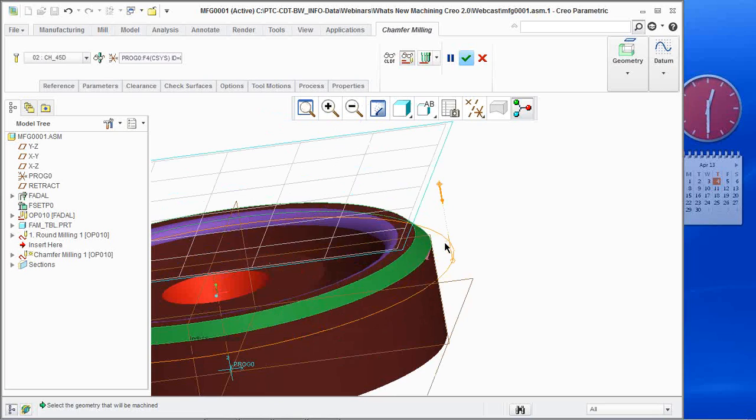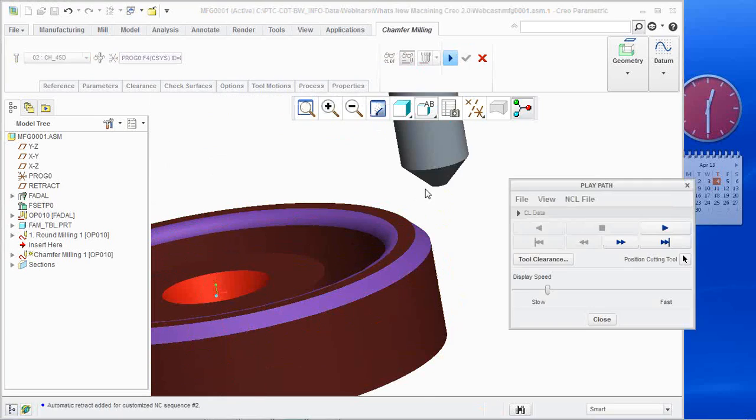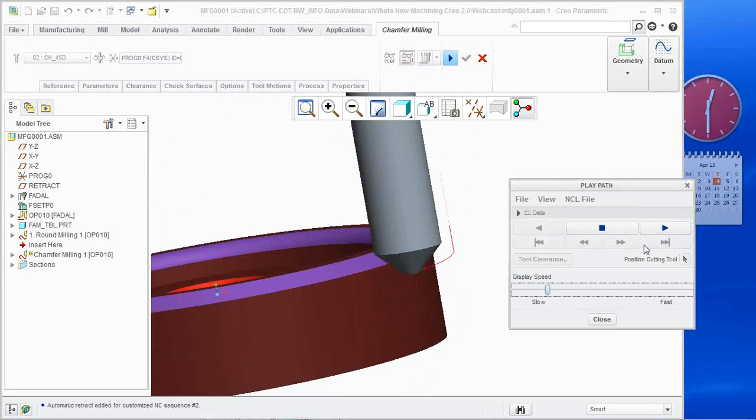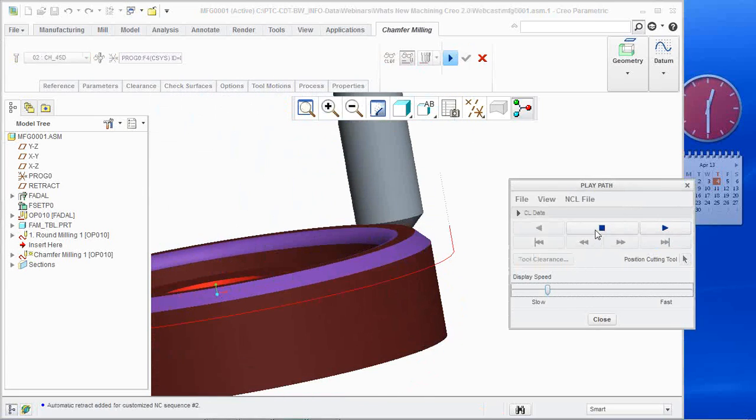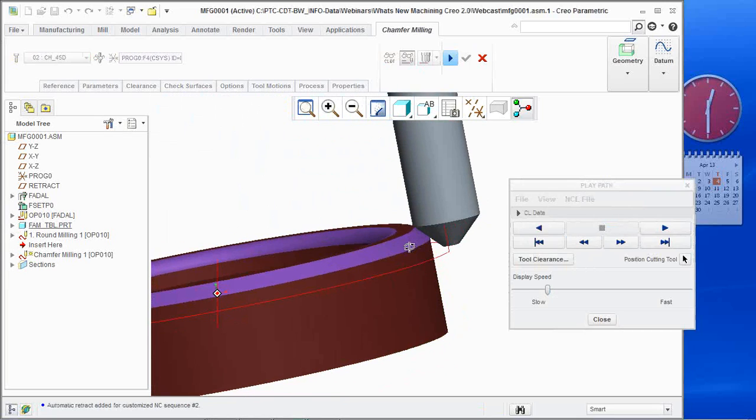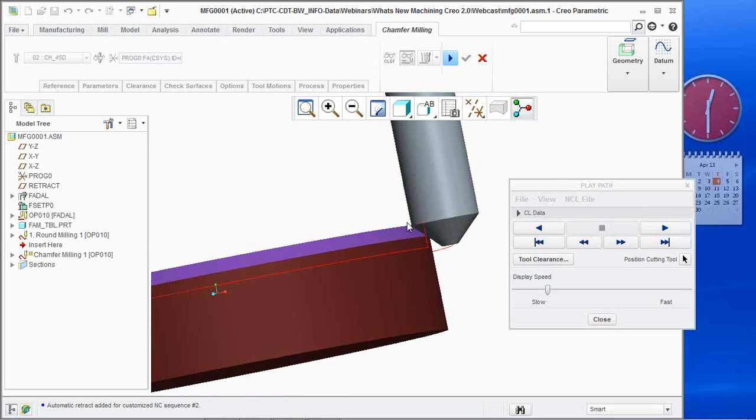I don't see that in my parameters. Again, it's probably because of my site file, but it's something that you can adjust. So when we saw the toolpath, you can see where it's cutting. Probably isn't the optimum spot, but you do have the ability to alter where it is machining. We probably want maybe that much flute on this side, and maybe right around there for that much flute on that side.